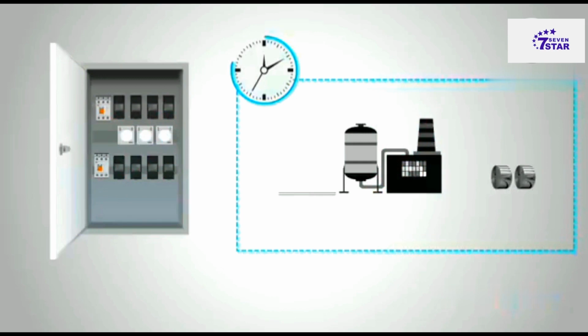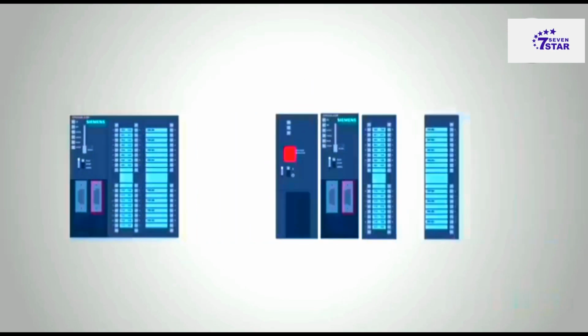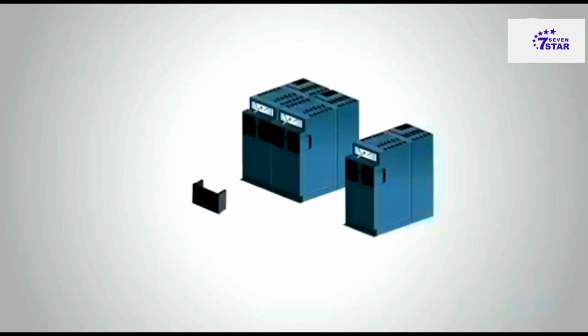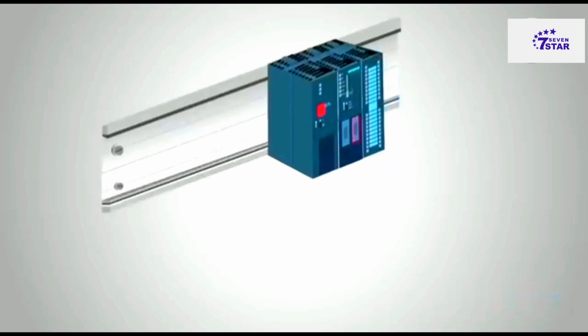The PLC. An installed PLC is deceptively simple in appearance. You have a CPU module and input-output devices, referred to as I/O. Sometimes the I/O is part of the CPU, and sometimes it is in other modules. The CPU communicates with the I/O. So in most systems they share a backplane that physically holds them in place and electronically connects them. In other equipment, the I/O modules can be miles away from the CPU and connected with data cables, so that the PLC is not limited to a single cabinet or even the same building.